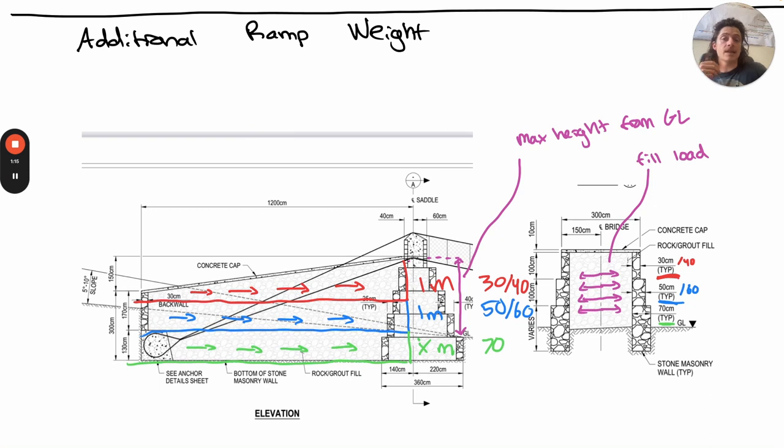In the basic design course, we assumed the entire ramp wall area was 30 centimeter walls. So we took the ramp wall area, we assumed its thickness was 30 centimeters, and that's how we got the volume of our ramp walls. This is numerically a much easier calculation, but wastes a lot of capacity. Or rather, doesn't engage or doesn't sharpen the pencil to think about this extra capacity.